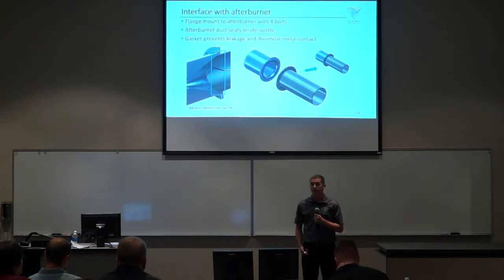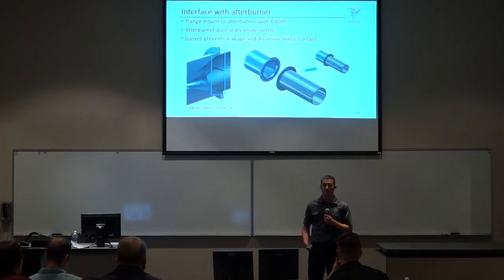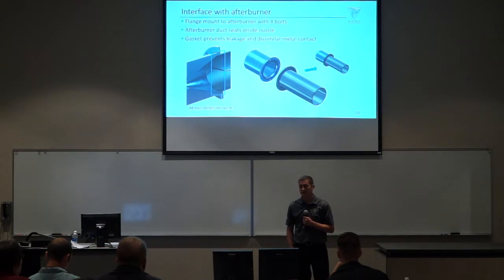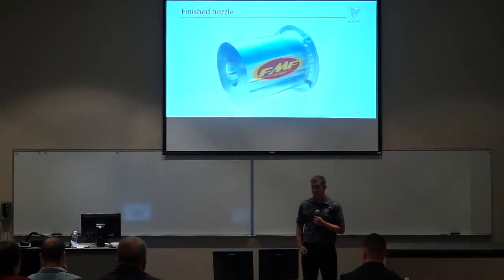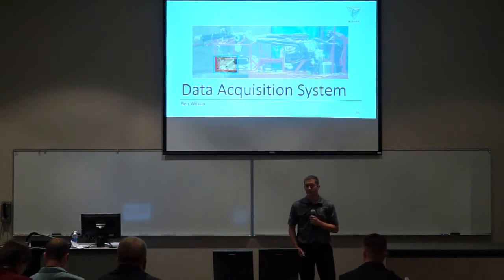This prevented leakage at this interface, and then also prevented dissimilar metal contact between the aluminum of the nozzle and the steel of the afterburner duct. So this is an image of the finished nozzle. And now I'll go into the data acquisition system.